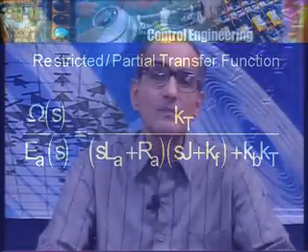Therefore, now go back to what I said about transfer functions earlier. A transfer function can be associated with its poles, its zeros and the gain coefficient. So, in this case, since the numerator is just a coefficient Kt, what about zeros of this transfer function? It has none.